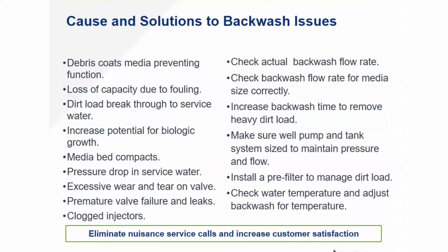Increase backwash time to remove a heavy dirt load. If you're dealing with excessively dirty water, dirtier than usual, backwash longer. You know the water in your markets, manage the water in your markets. Make sure a well pump and tank system are sized to maintain pressure and flow for the system. You may have to go to the extreme of installing a pre-filter to manage that dirt load. To be honest with you, if I can save water and use a cheap pre-filter to keep that dirt load out of my softener and keep it doing what I want it to do, which is exchanging mineral content, I want to manage my dirt load with a cheap pre-filter.